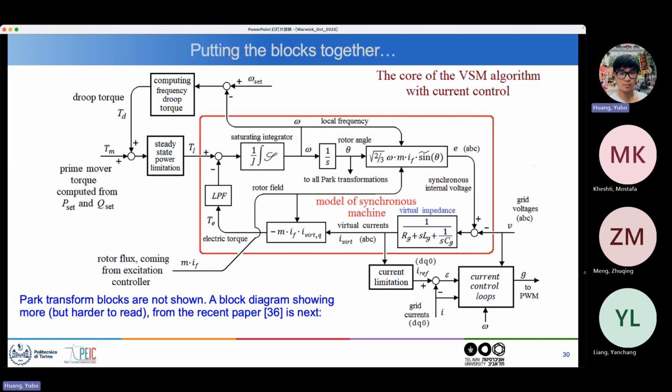This is actually something that we encounter. To prevent that, you put also a series capacitor. But the series capacitor, you choose it huge, so that at the frequency of 50 Hertz it is negligible. It does nothing at 50 Hertz, or at 100 Hertz, or at 150 Hertz. But it is there to prevent a DC current in steady state.